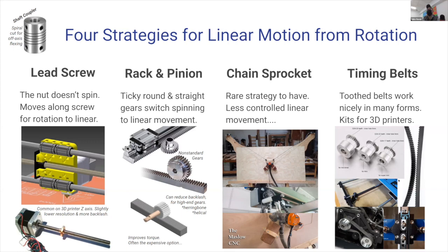They've got these teeth, they go along these gears. And as long as all of these mesh and are the same tooth density, the same size, this can be a really nice way to get motion to bend around in lots of different directions. You can use a couple of gears like this. Sometimes they have edges on them to keep the belt from sliding. Sometimes they don't. You can use an idler pulley like this, where it sort of presses it in from the side and holds it all together. All of those are good tricks with mechanisms like this. So you can have a good connection with a timing belt. You can also sort of just clamp it down on the edges.